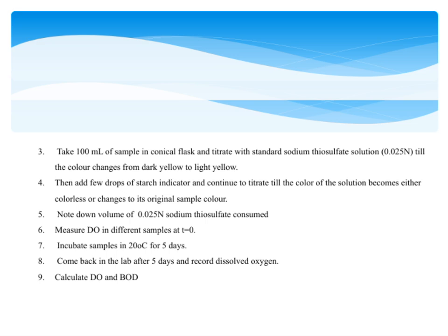Next, we add a few drops of starch indicator. This helps us see the exact point where the iodine is fully reduced. We continue titrating until the solution becomes either colorless or returns to the original sample color. It's important to note the volume of sodium thiosulfate used during this titration, as it will be crucial for calculating the dissolved oxygen in our sample.